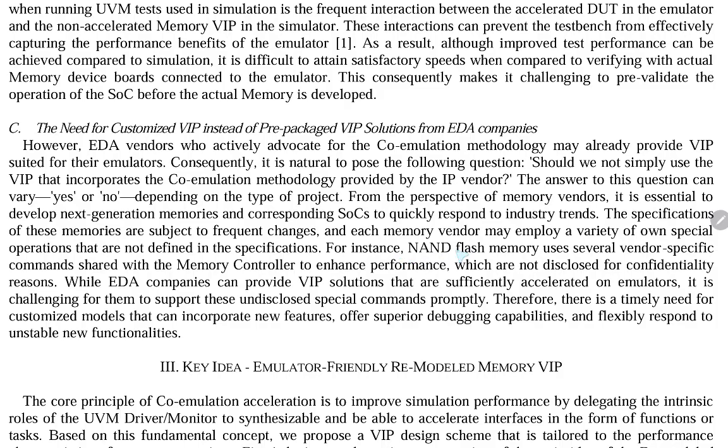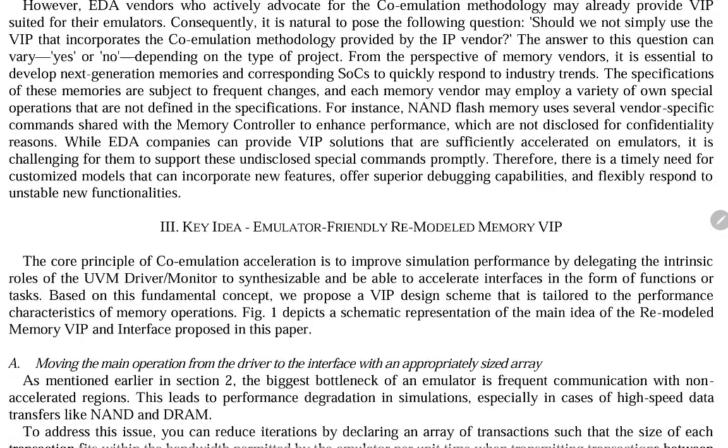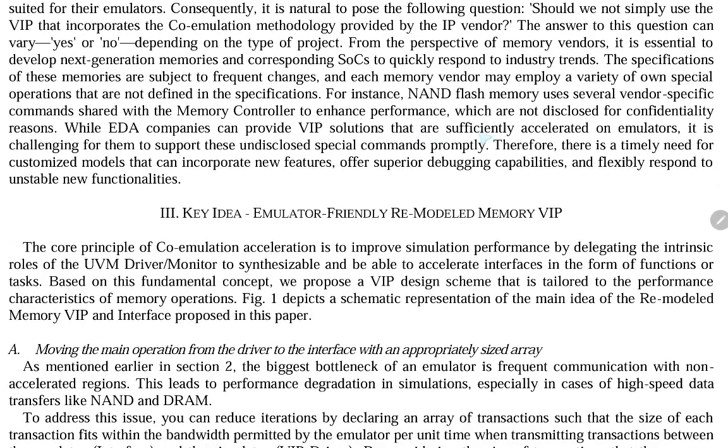For instance, NAND flash memory uses several vendor-specific commands shared with the memory controller to enhance performance, which are not disclosed for confidentiality reasons, while the EDA companies can provide VIP solutions that are sufficiently accelerated on emulator. It is challenging for them to support these undisclosed special commands promptly.